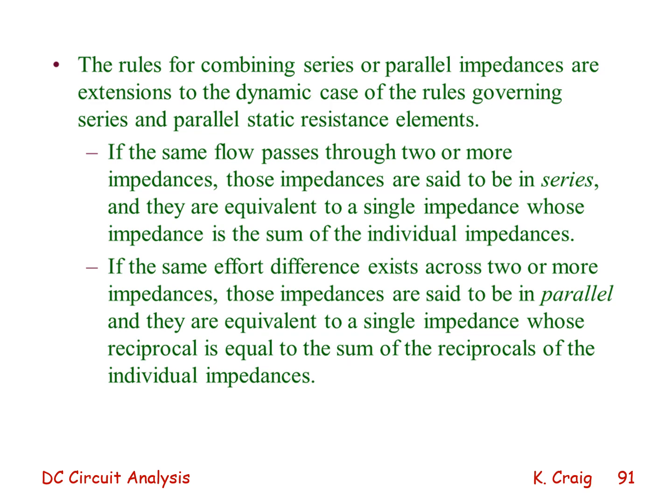If the same effort difference exists across two or more impedances, those impedances are said to be in parallel, and they are equivalent to a single impedance whose reciprocal is equal to the sum of the reciprocals of the individual impedances.